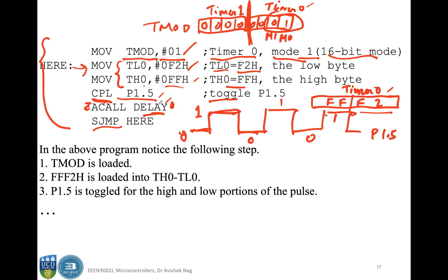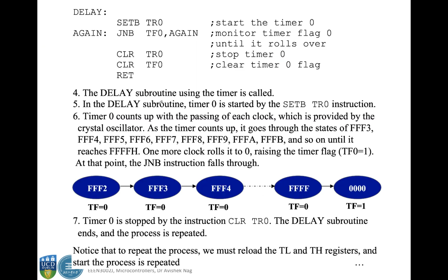Now let's focus on the delay part. What is happening in the delay part? The delay subroutine is using the timer. Let's say you have already loaded your timer 0 with FFF2, as you saw.